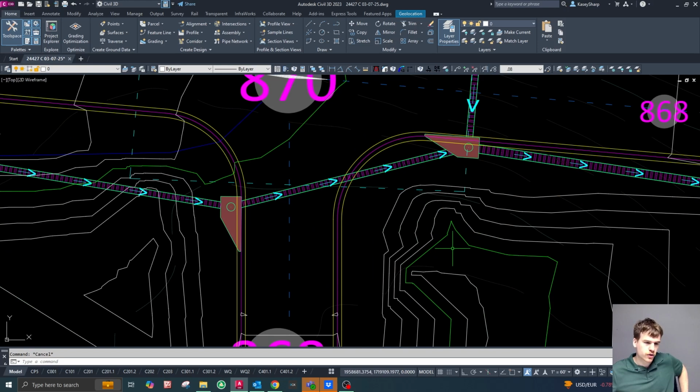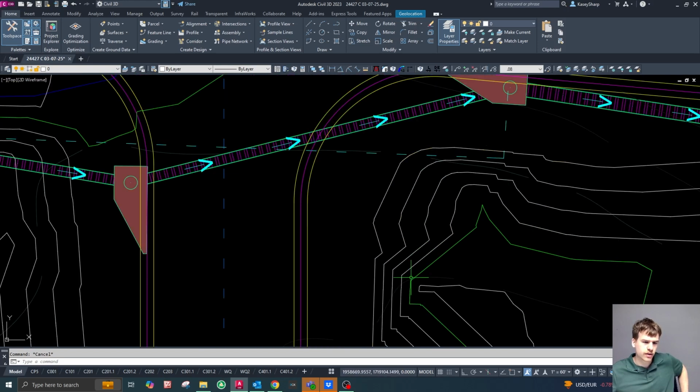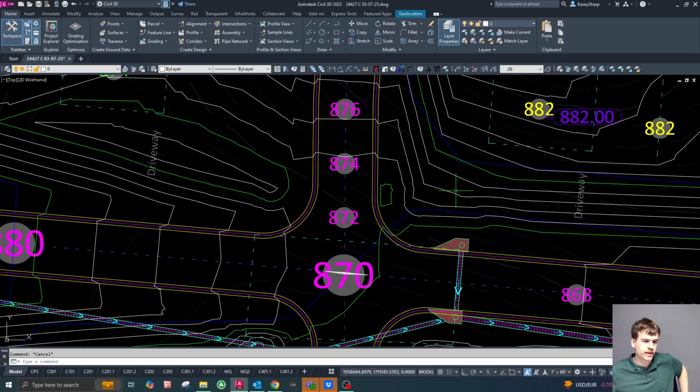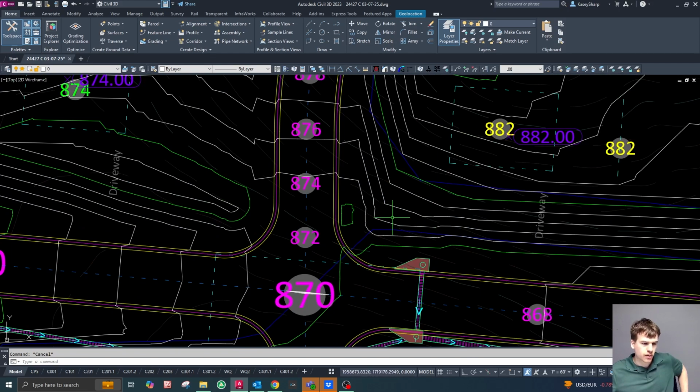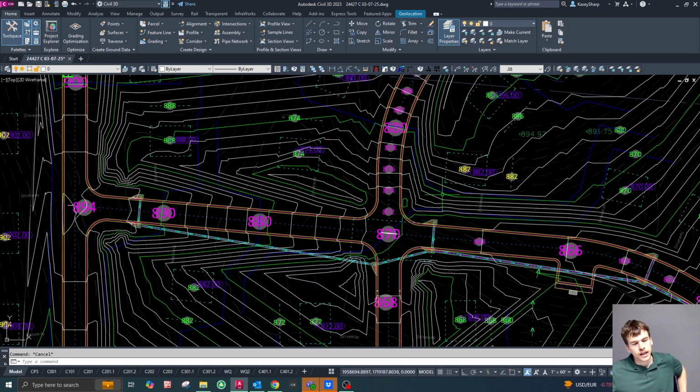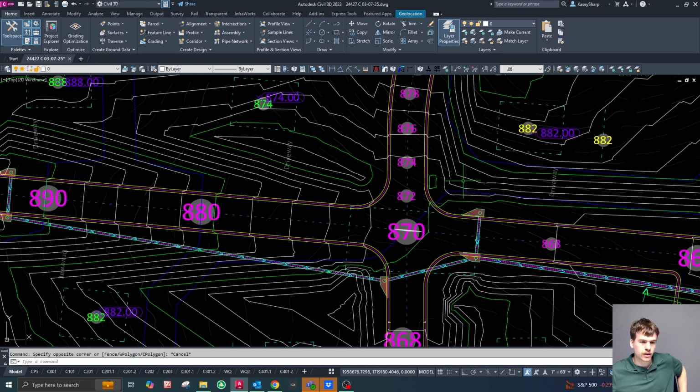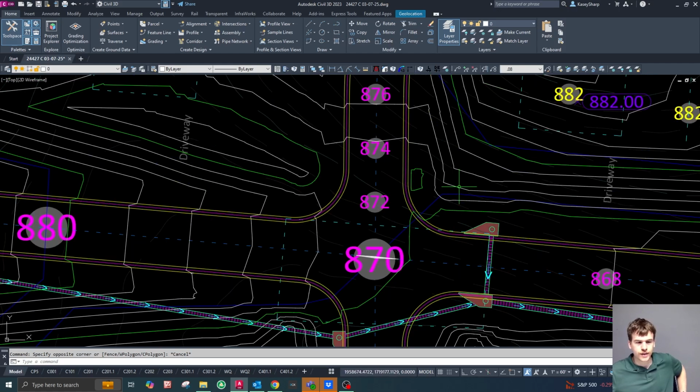And then as you can see here at the corners, even though there were those bow ties, it still does a decent job of tying in the contours. You might have to edit and change things as needed, but see up here where there was no bow tie, it does a pretty good job of following or interpolating and outputting a good surface for you. And then, like I was saying, those weird funky regions, which were right here and right here, along the greater than 90 degree angle turns, didn't really result in anything weird in the surface.